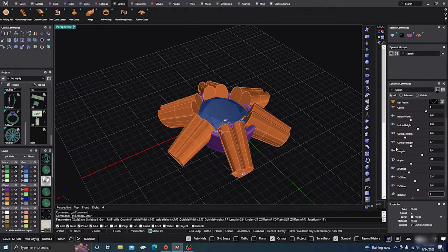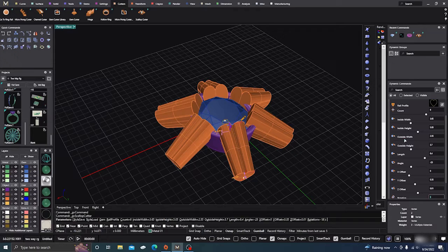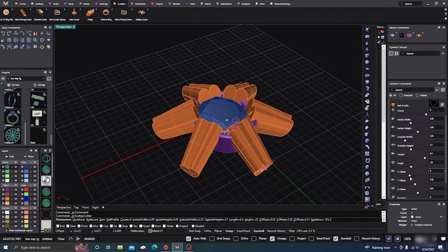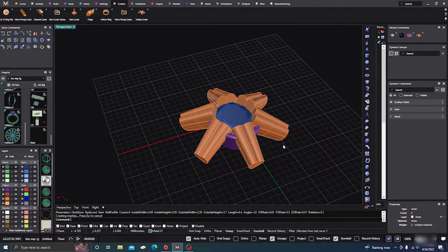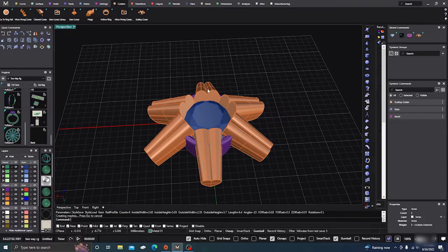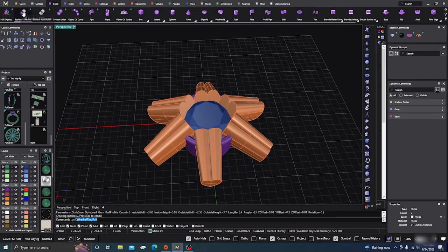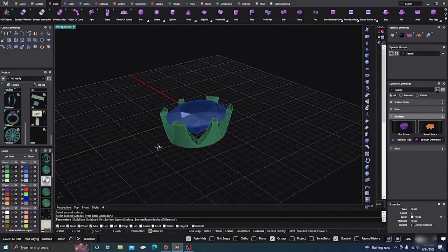and we'll just do a boolean here, something like this. We'll take the length, and just extend. Where is it, offset X? No, that we want at 0. Yeah, the Y offset, we'll bring it in a little bit. Alright, and then we'll just go ahead, enter, and do a little cut just so you can see what it does. Go to your tools menu, solids menu, boolean difference, select our bezel, hit enter, select our cutters, and hit enter, and there you have a nice little scalloped head.